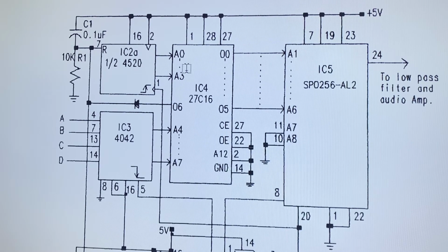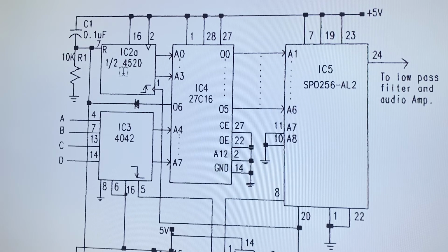So this is one basic way of addressing a memory with 16 blocks of memory, with this counter acting as a program counter, because this one is addressing or scanning the memory, and this one is selecting the block of memory.